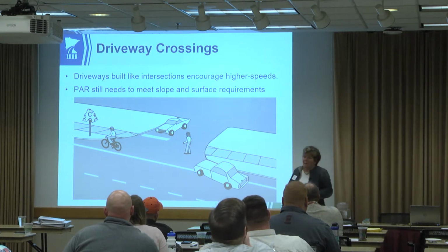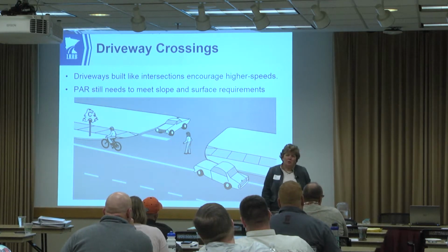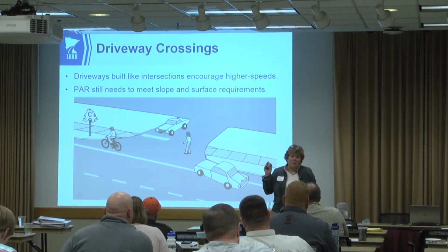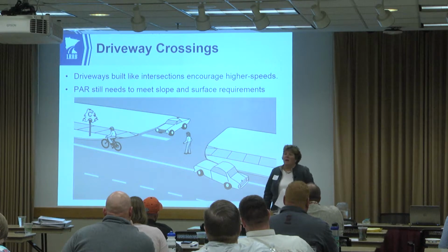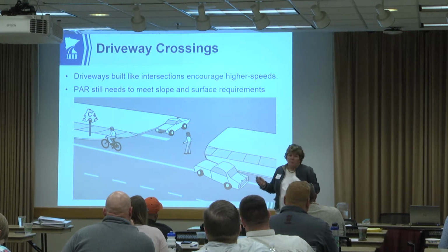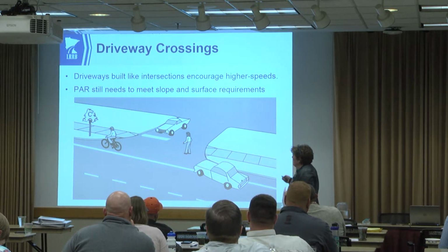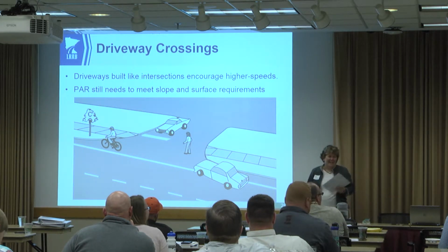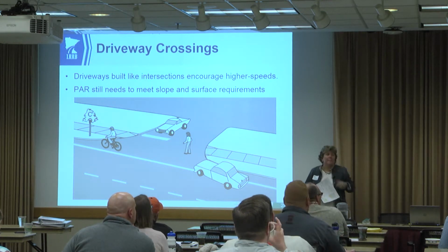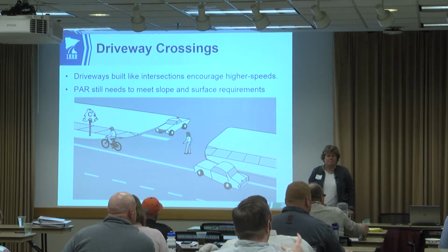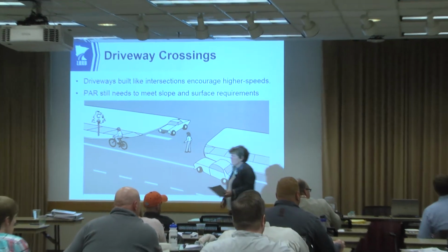Brady and I both live by Wayzata. I pass tens of these on my way to church and the bank every day, and they all look just like that. There is no requirement that you maintain the sidewalk through a driveway, and there's no requirement that you put domes there or a pedestrian access ramp. The ramp would be required if, for some reason, you had an elevation change such that this exceeded 5%. Then you would put a ramp there, right, Brady? Right, so I think we get a lot of questions about are truncated domes required at this location. They're not required at driveways, but if you end up having to put ramps in there, then you put the domes in.